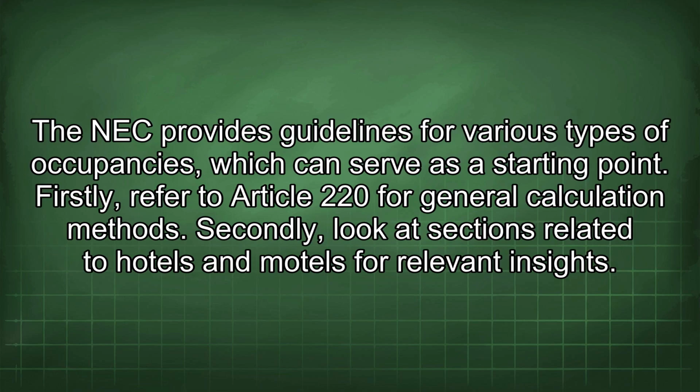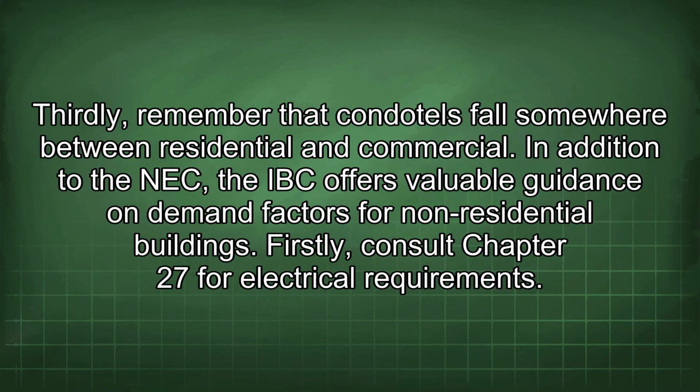The NEC provides guidelines for various types of occupancies, which can serve as a starting point. Firstly, refer to Article 220 for general calculation methods. Secondly, look at sections related to hotels and motels for relevant insights. Thirdly, remember that Condotels fall somewhere between residential and commercial.